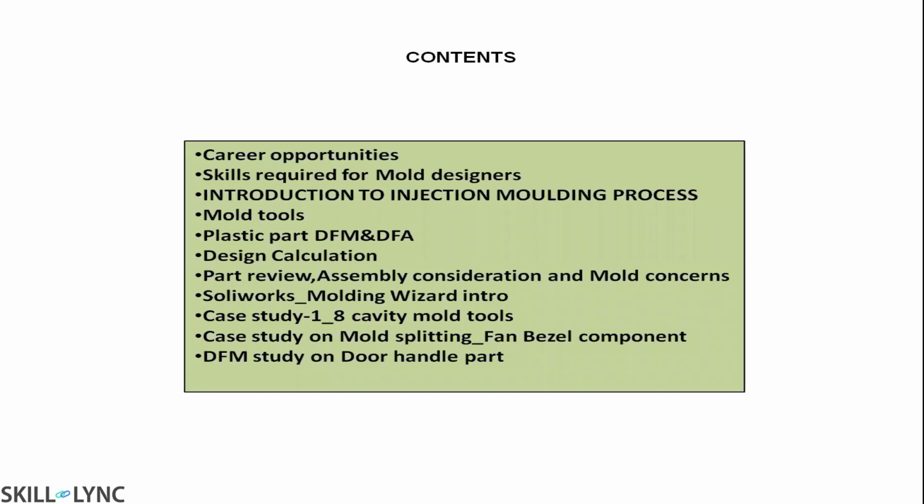After that, the second session of the webinar will be on the SolidWorks molding wizard intro on the 3D model. I will show some 8 cavity mold tools, just for your visualization of how the mold will be. I am not going to design now. I am just going to teach you what things are involved in mold design. I will show you the 3D model, and second, how to do core and cavity extraction of the fan bezel component, and a DFM study on another door handle part.